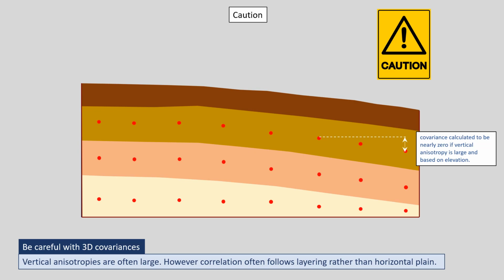Hence, normally I don't build three-dimensional covariance matrices. There may be exceptions if I've got pilot points arranged on a regular grid, but normally the difficulties of handling pronounced vertical anisotropy make this too prone to getting correlations wrong when building a 3D covariance matrix.